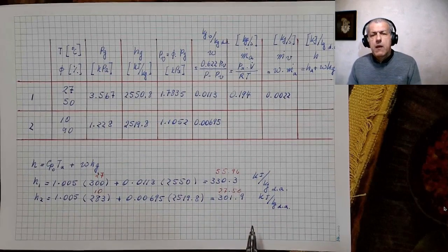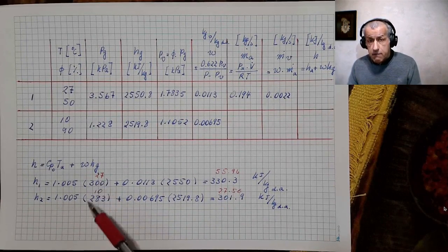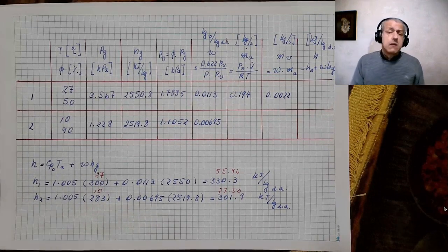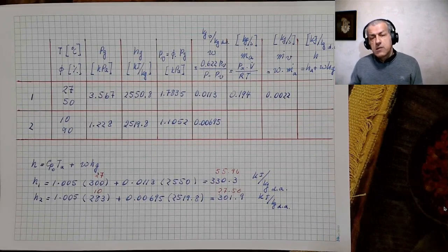In some air conditioning problems, they don't use either of them. But what they do is that they assume their base temperature to be minus 20 degrees C, since most air conditioning problems are concerned with the temperature range from minus 20 degrees C to, say, 50 degrees C. So they place the base on minus 20 degrees C and then do all calculations in that range.